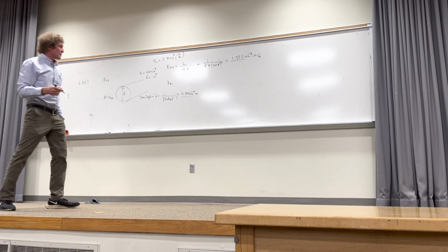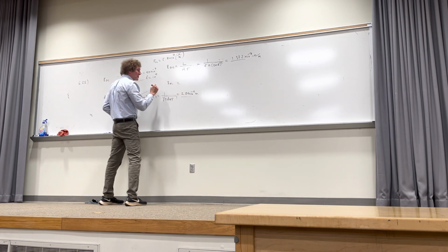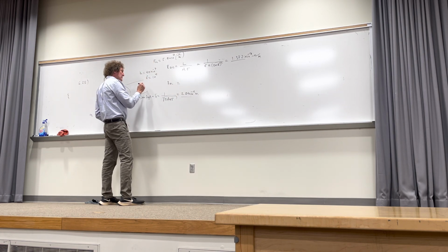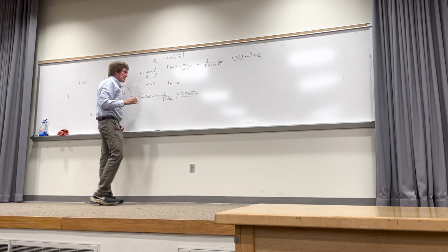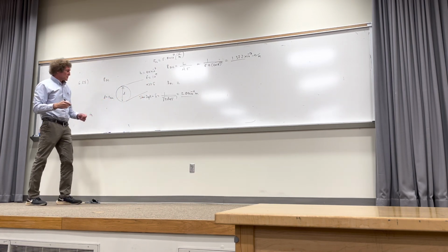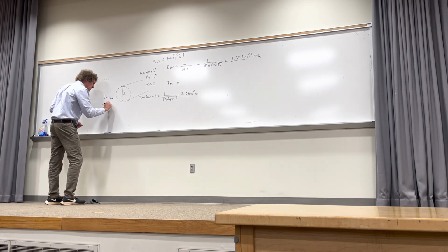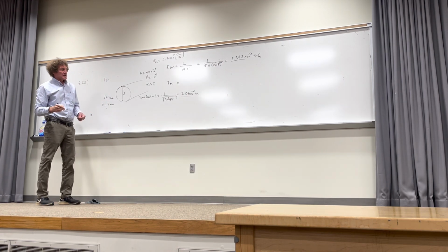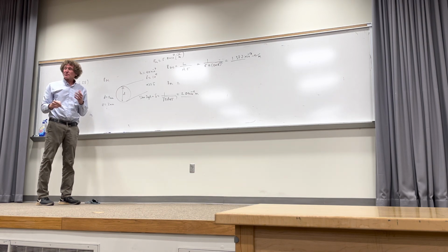Now, when you're doing an AC resistance calculation, in order for the approximations to work, you have to make sure that the radius itself is much, much greater than the skin depth. And in this case, it's obviously true, because the radius is 2 millimeters, so 2 millimeters is much, much greater than 2 microns. It's 3 orders of magnitude larger. Do y'all follow me on this?